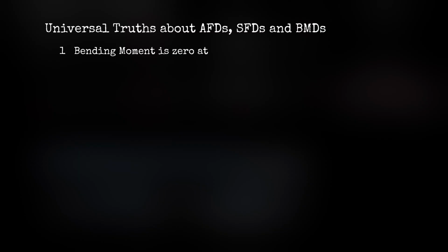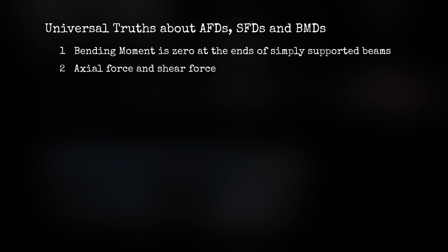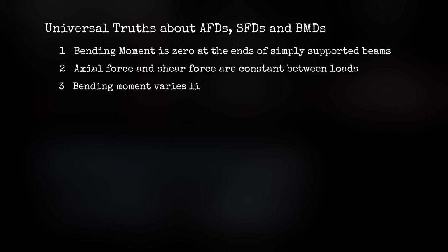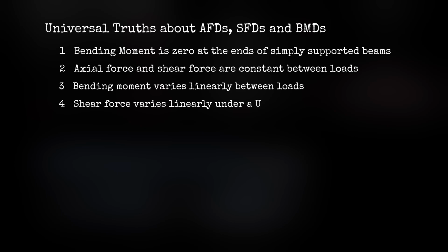1. Bending moment is 0 at the ends of simply supported beams. 2. Axial force and shear force are constant between loads. 3. Bending moment varies linearly between loads. 4. Shear force varies linearly under a UDL. 5. Bending moment is parabolic under a UDL.